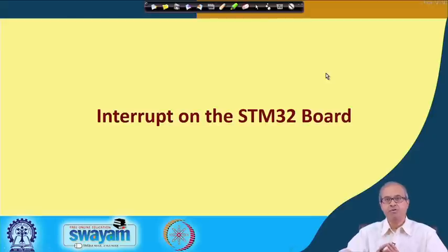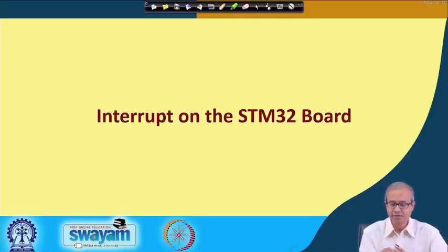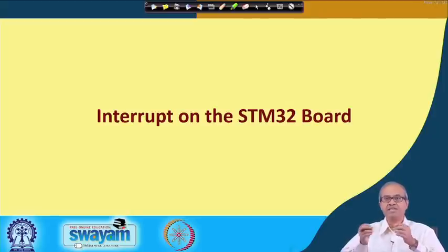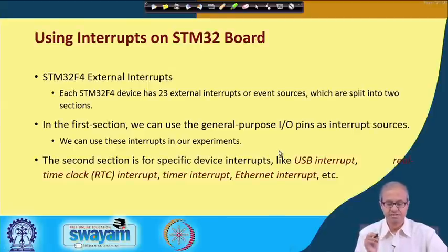Okay. Now, let us see what are the kind of interrupt facilities that are available on the STM32 board, because you know that in many applications wherever you are interfacing some devices, there will be some devices which can be generating some interrupt signals from outside. So, I mentioned that in the ARM processors there are many interrupting sources. In fact, any of the port lines you can use as an interrupt input, right. So, let us look into a little more detail.